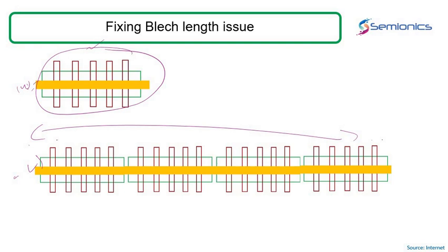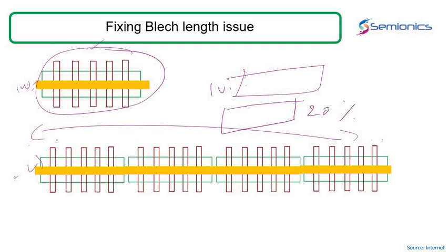So in scenarios like this, you have to ensure the width of the metal is right. Whenever you're calculating EM, say if the width you have to use based on your calculation is 1 micron, the rule of thumb we generally follow is to go 20% more than what is required, just as a precautionary measure, when you're arranging the bunch of devices over here. So I don't think this length of the metal will be sufficient.